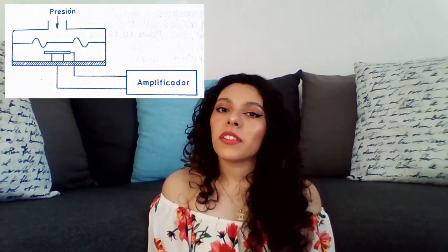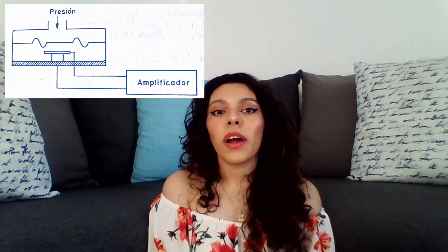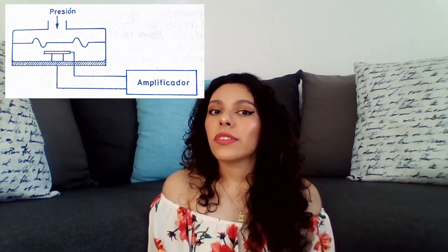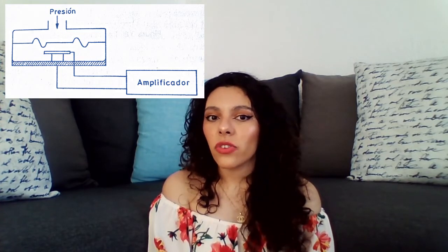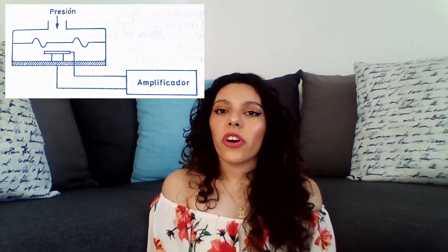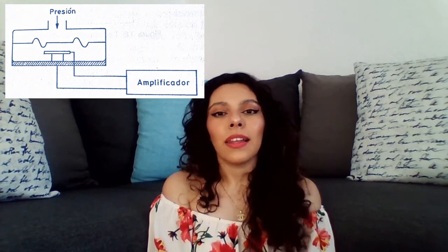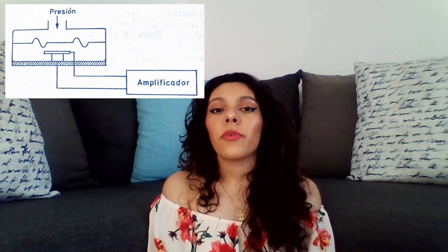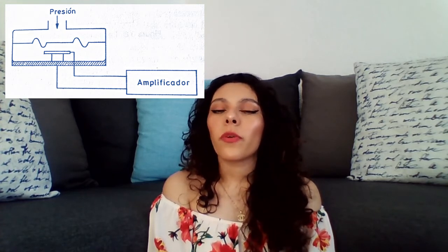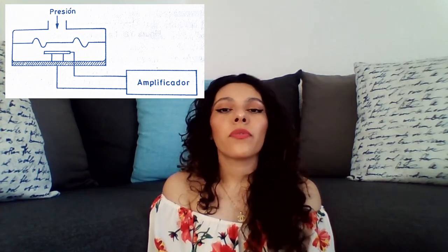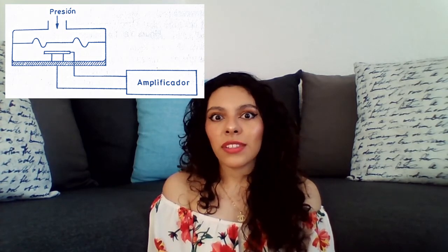Piezoelectric elements are crystalline materials that, when deformed, generate an electrical signal. Quartz and barium titanate are widely used in these elements and withstand up to 150 Celsius in continuous service and 230 Celsius in intermittent service. They are small, light, and of a robust construction. Their response signal to a pressure variation is linear, and they are suitable for making dynamic measurements thanks to the fact that they can give frequency responses of up to 1 million cycles per second.